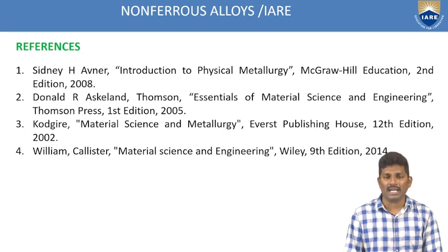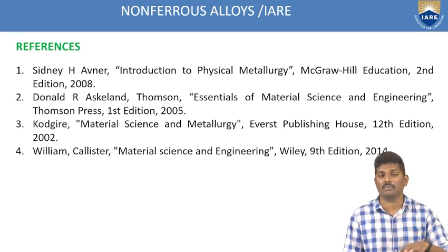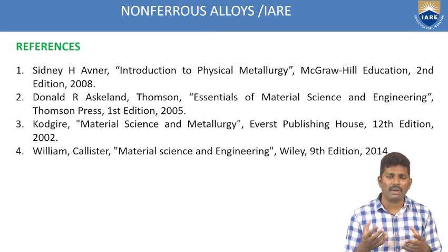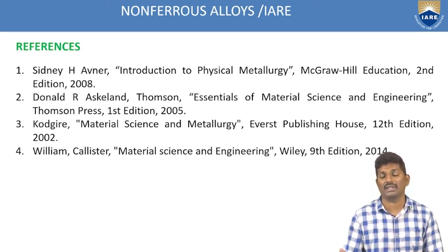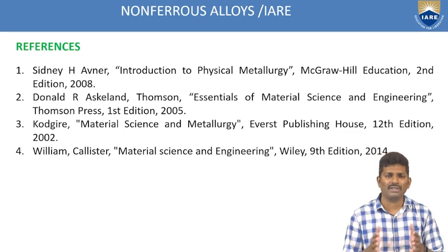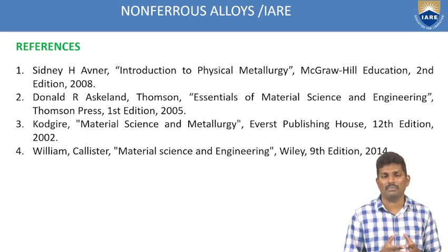By seeing the type of structure, how the graphite flakes are arranged, and how these graphite flakes are surrounded by the pearlite. If you see the dark graphite surrounded with pearlite, then it is called grey cast iron, since it looks grey. Similarly, if you identify any white patches on the microstructure which are again surrounded by pearlite, then that type of cast iron is called white cast iron. So you have different types of irons based upon the microstructure and the composition. These all vary depending upon the composition. That's why composition is very important.